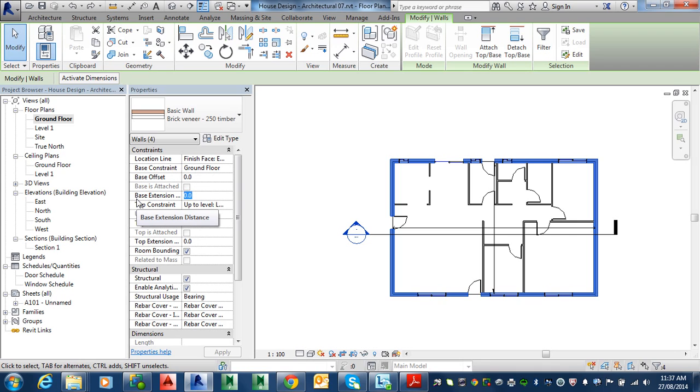So that's why we're leaving it a little bit above it, and we're just calling that basically the mortar joint anyway. It's 10 millimeters. So we're leaving it 10 millimeters above for that reason. So it's got minus 20. Revit is sort of full of workarounds, and this is just one of them.